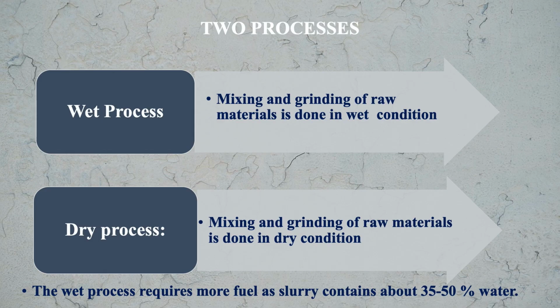The main difference here is the energy required. That is, how much energy or fuel is required in the two processes. In case of the wet process, more fuel is required because the slurry has a lot of water, about 35 to 50%. So for evaporating this water, more energy or fuel is used.